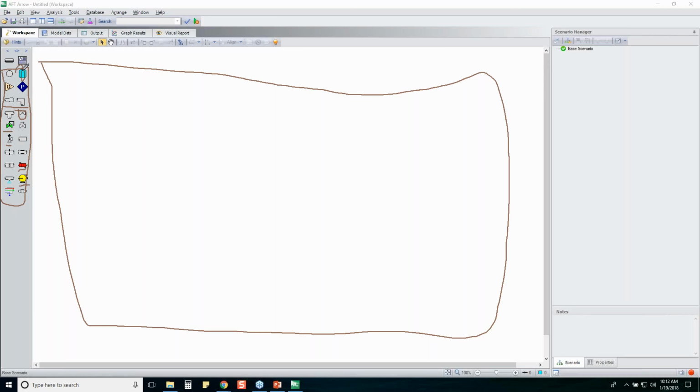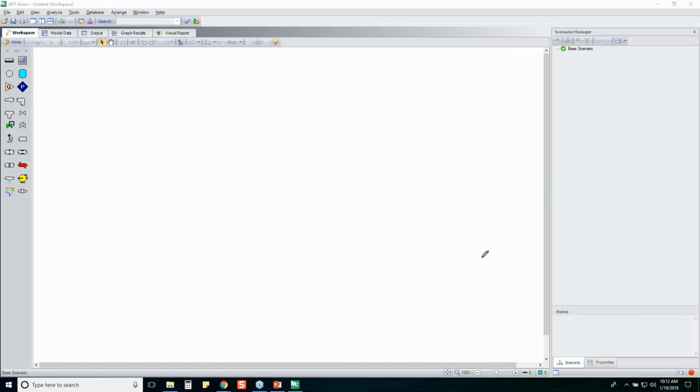You've got a tank boundary condition, assigned pressure where you know what the pressure is directly, or you can do an assigned flow junction. If you know what the flow rate is, you can model that as a known flow boundary. So each of those components are what you use in order to build a model of your system. Now, when you don't know where to start, the thing to focus on is the red status light down here in the bottom right corner. Red means stop, green means go. If you click on that red status light, it's going to pull up a checklist of items that need to be completed before you can run your model.